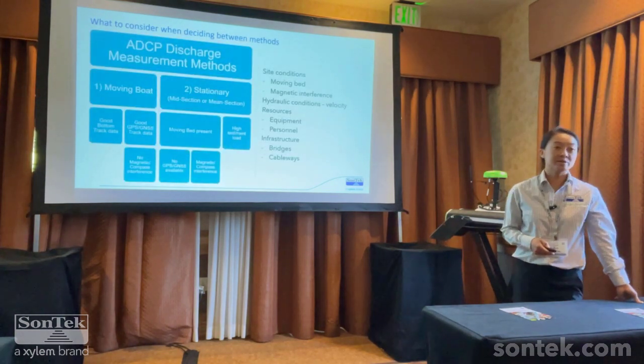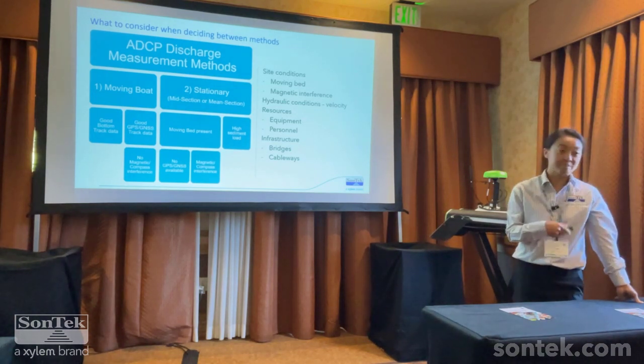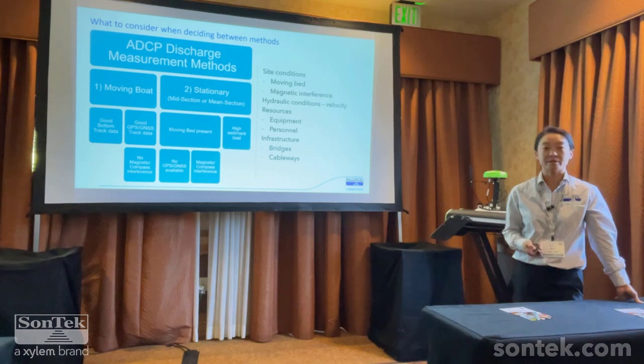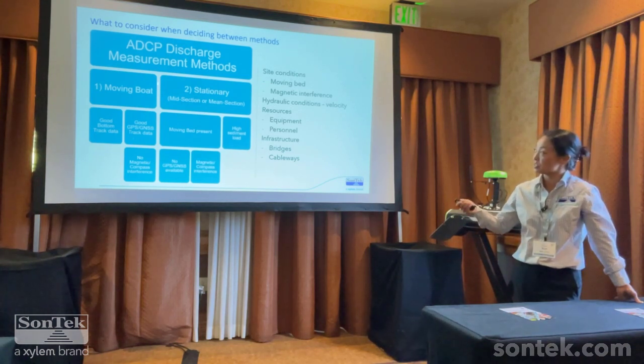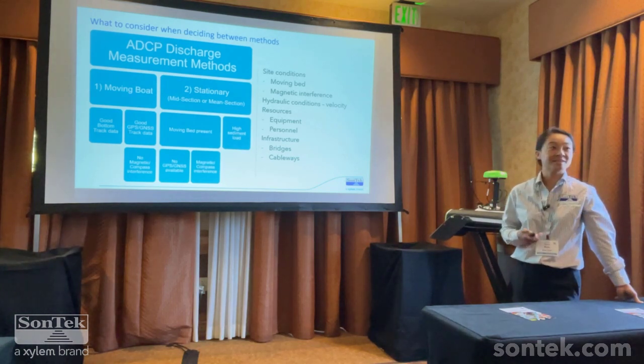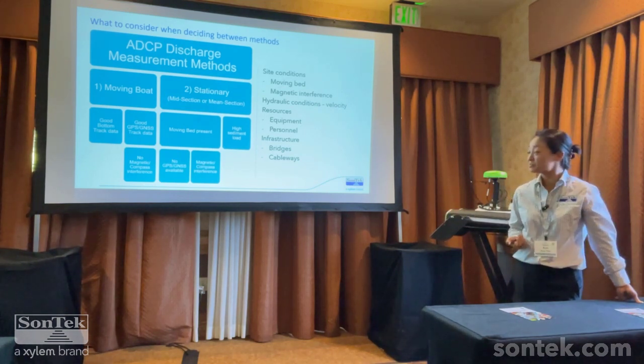So now you're probably wondering, well, when do I use one versus another? And I did mention before that the moving boat is generally a little bit quicker than a stationary measurement. So when you go to a site, many people kind of default to a moving boat situation, which is kind of to the left here. So when you have a site with good bottom tracking, good GPS data, no magnetic interference, kind of your ideal site, and you know that nothing's going to go wrong, you can use the moving boat method. That's going to be just fine.